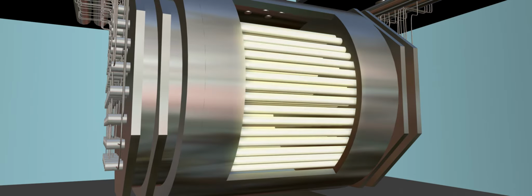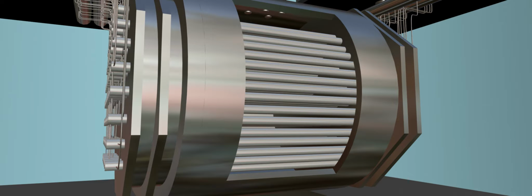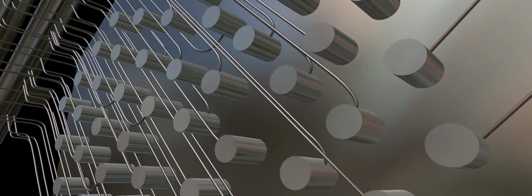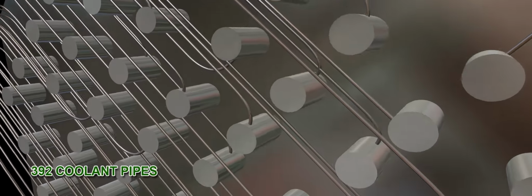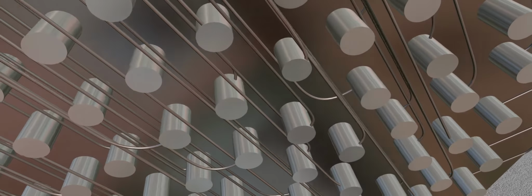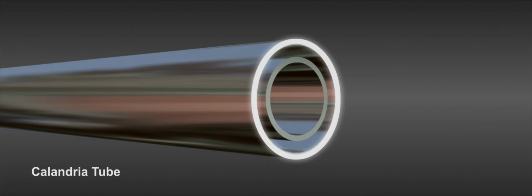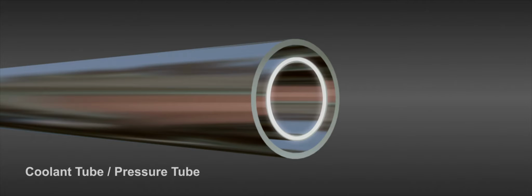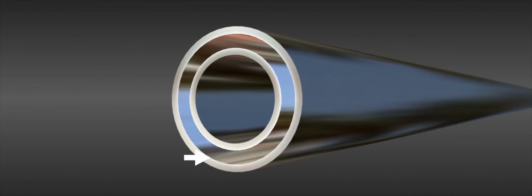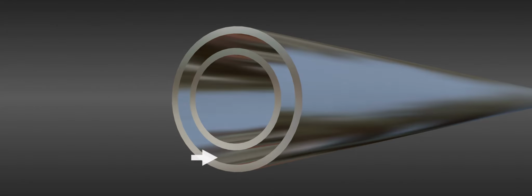A set of pipes called coolant channels pass through the calandria and end shield assembly. The metal used for these pipes is an alloy of zirconium and niobium. 392 such coolant pipes exist in a 540 megawatt PHWR. Each coolant assembly, in fact, has two concentric pipes, one inside the other. The outer pipe is called the calandria tube, while the inner pipe is called the coolant tube or pressure tube. For thermal insulation, carbon dioxide is filled between these pipes.